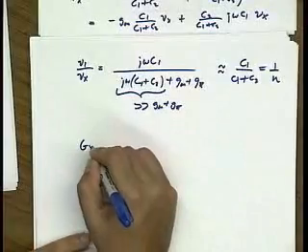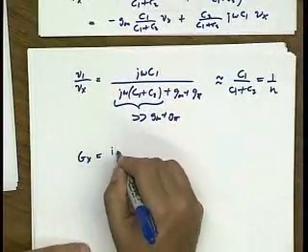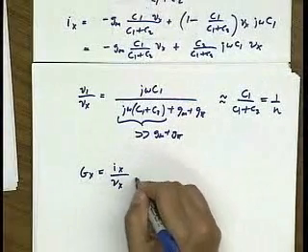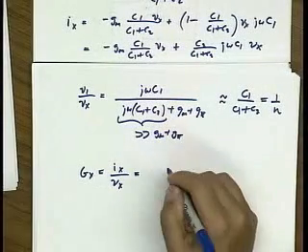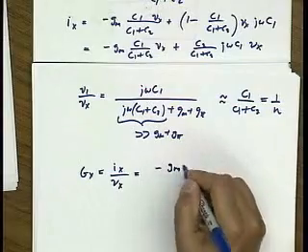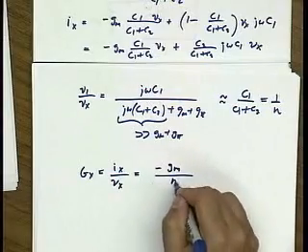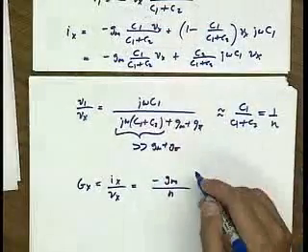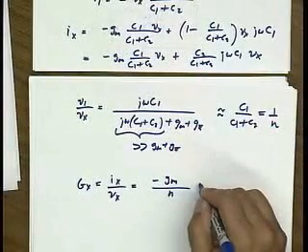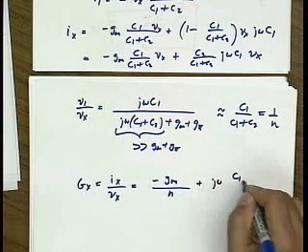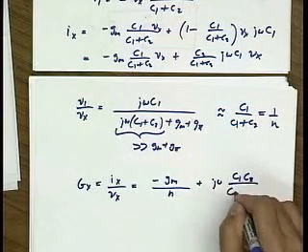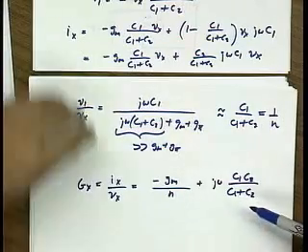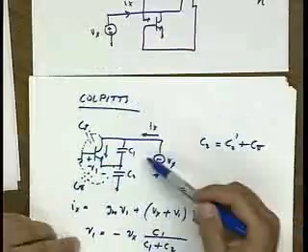So if we just now go ahead and substitute from up here, if we've done everything correctly, the answer is that I have basically a real resistance, which is Gm over N. This is Gm, this is N, basically. And I have an imaginary component, which you'll observe is just a series combination of C1 and C2.